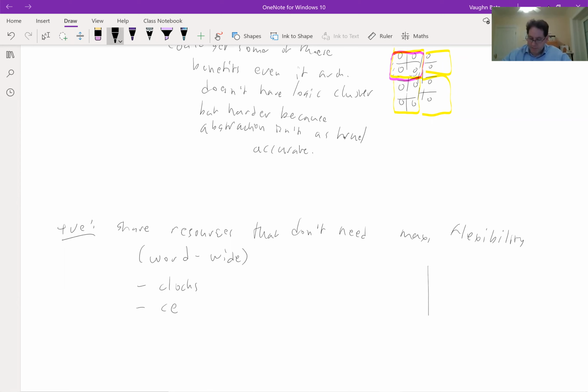So I think of some number that I've stored in a register, because it was actually in several 1-bit registers. So maybe I've got a 5-bit number. The data input to every one of those bits is different. You think back to your lab 1, what you were storing into every bit of a word would be different, but the clock is going to be common. And whether or not you enable that clock is also going to tend to be common.